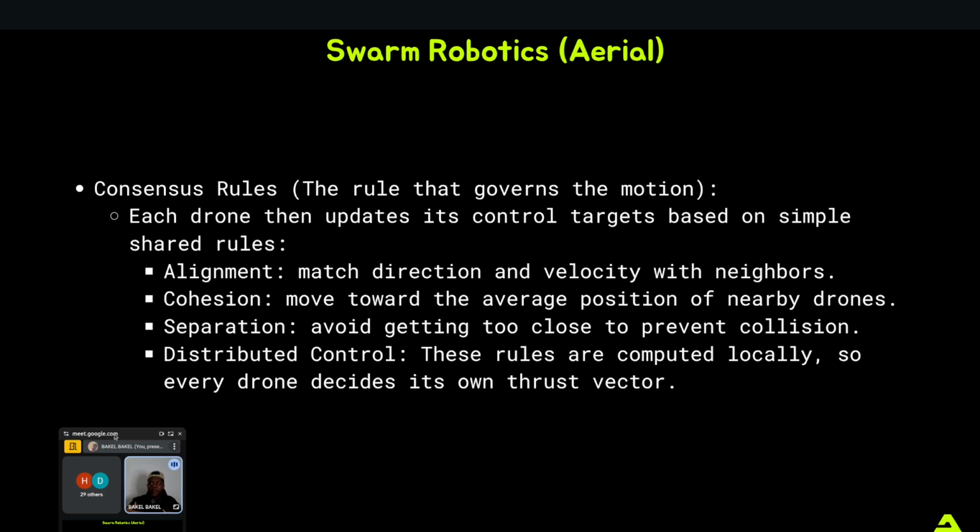As you turn it on, first, all of them broadcast their position and their orientation. As they broadcast, they also receive the position of the neighbors. They know their position, they know the position of their neighbors, so they are able to compute the distance. And the moment they all see the distance is 1 centimeter, they all engage velocities to spread out.